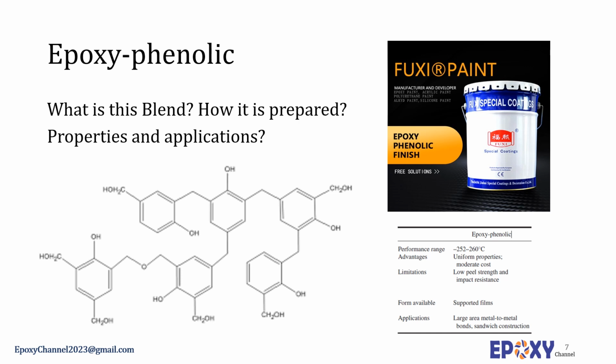Adhesives based on epoxy phenolic blends are good for continuous high temperature service in the 175 centigrade range, or intermittent service as high as 260 centigrade for short terms. They can be used even at 370 centigrade. They retain their properties over an extended temperature range. Epoxy phenolic adhesives are exceptional in that they have good adhesive properties at both elevated and low temperatures.